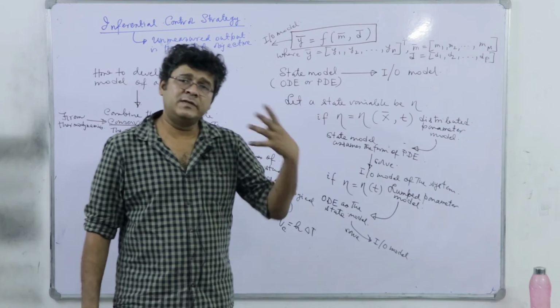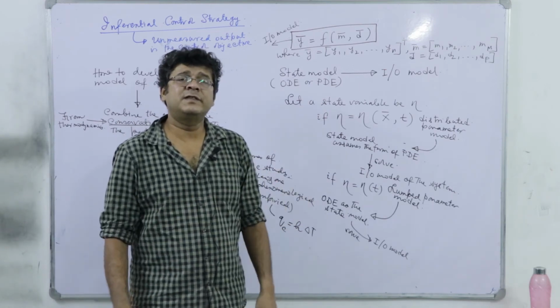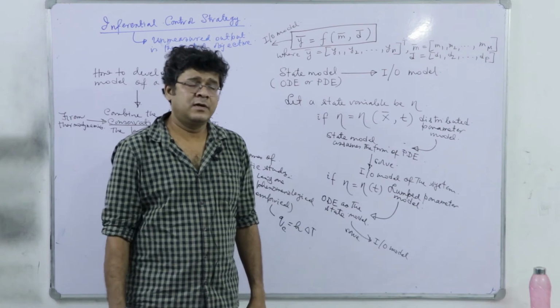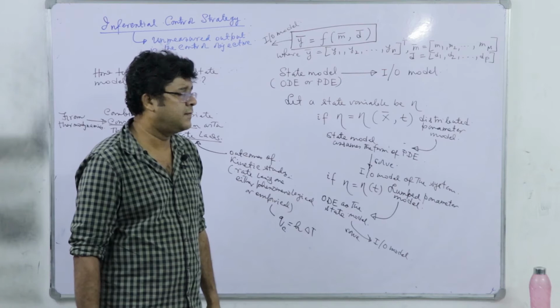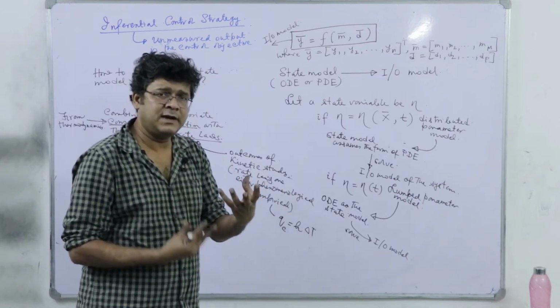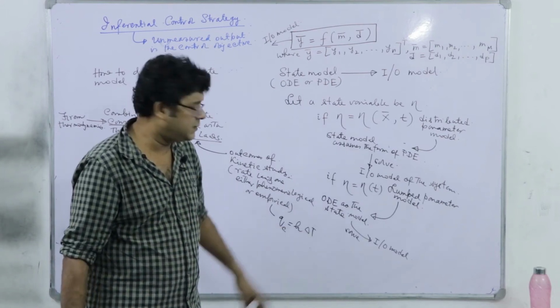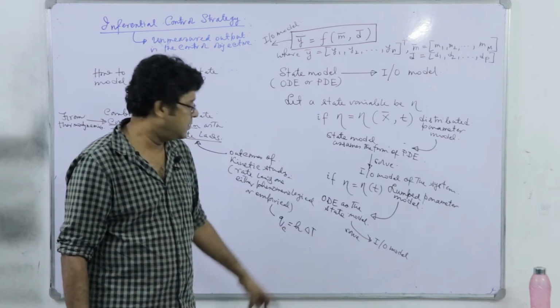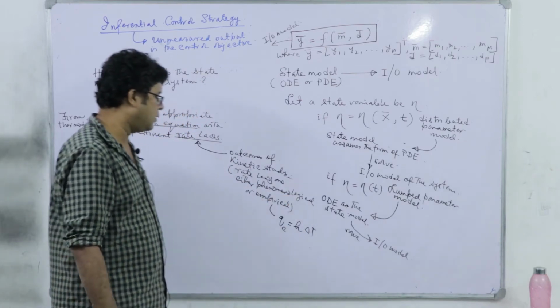What we do? We simply combine this Kf with the delta, which is the effective film thickness. So, Kf divided by delta, we lump it into H and we generate this rate law as the convective flux, H into delta T. So, this is an empirical rate law, okay.